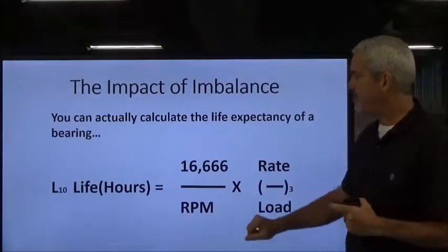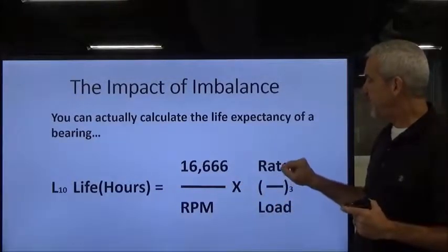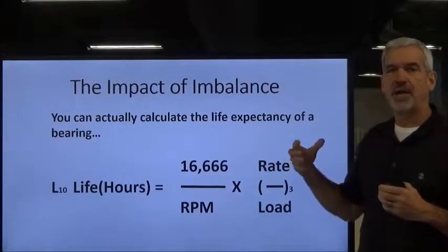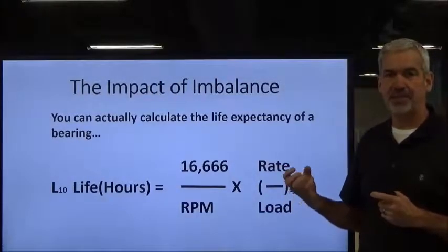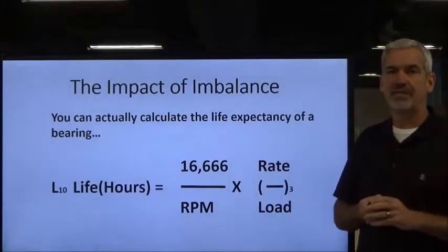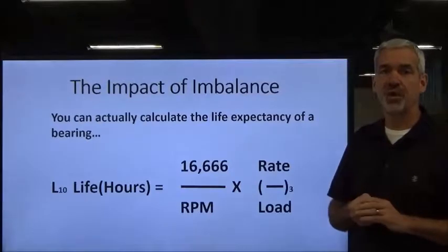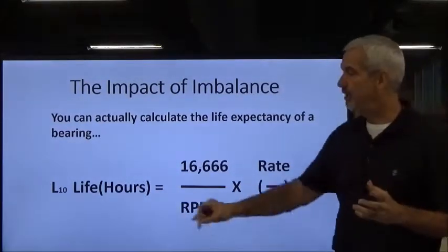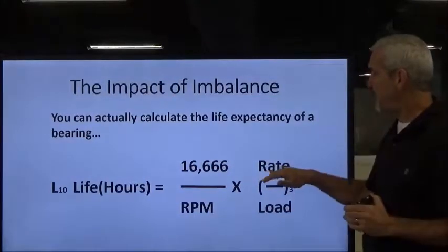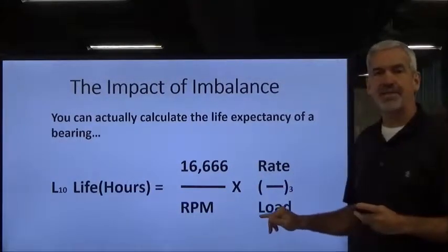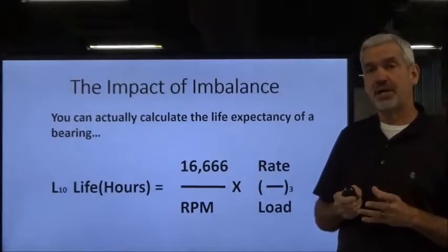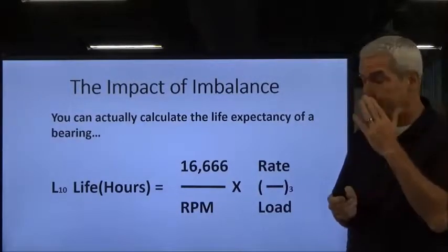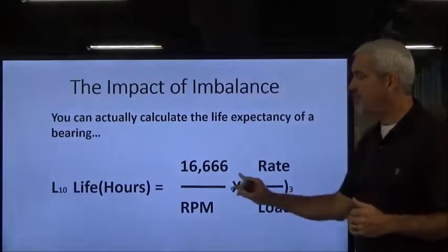So we divide that number, then we take the load rating of that particular bearing, and every different style and model has its own load rating, what it's expected to be able to carry and perform and live its full life. Okay, so we've got that rating, and we divide it by the amount of load we are actually putting on the bearing itself, okay? And then we're going to cube that and multiply these two.